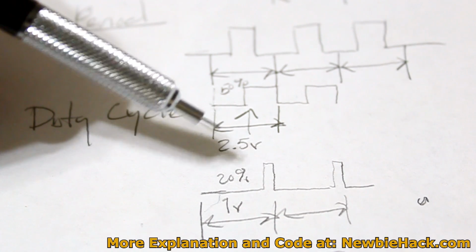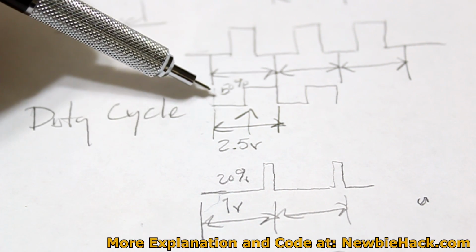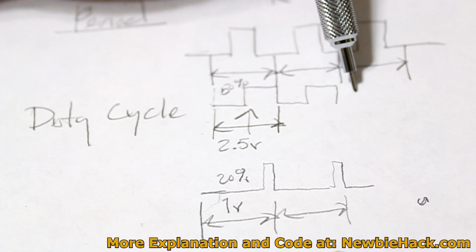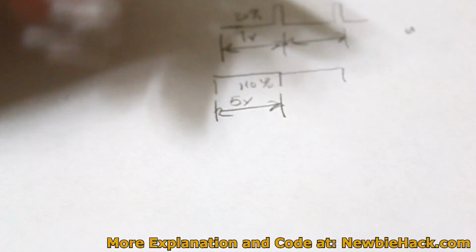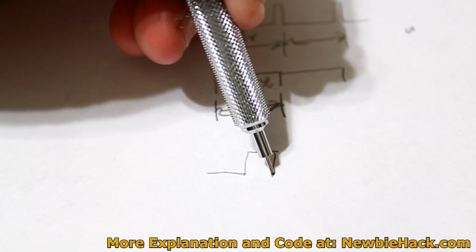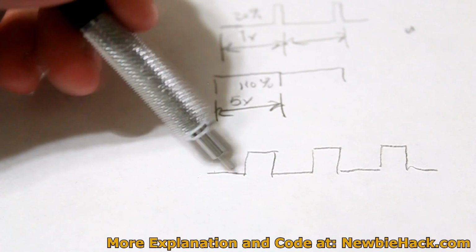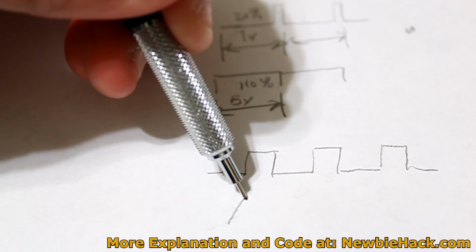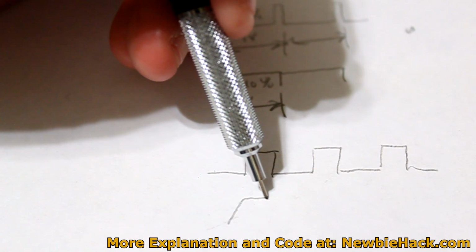We've already learned in the converting AC to DC that we can take these pulses and produce a nice stream of voltage using capacitors. In PWM, if you have a pulse like this, the first time the capacitor gets a charge, it's going to take the voltage and keep it, and then when it sees no more voltage, it's going to start ramping down.